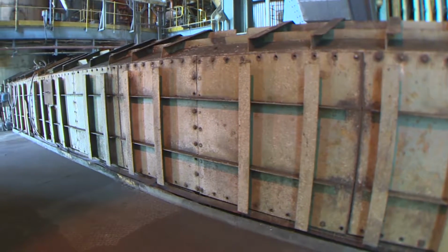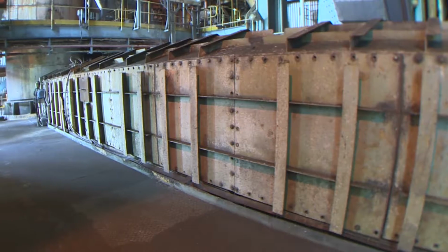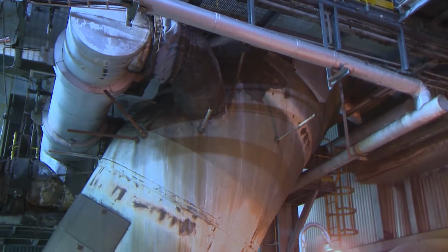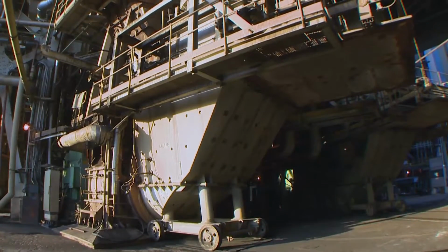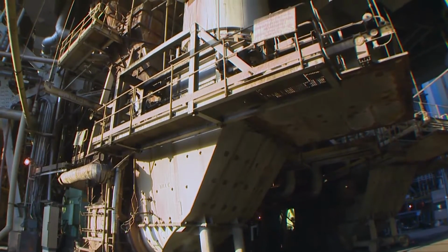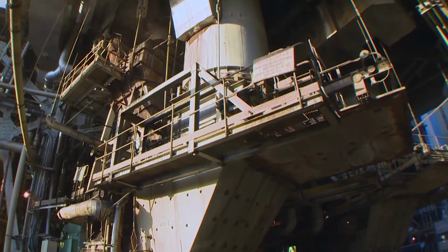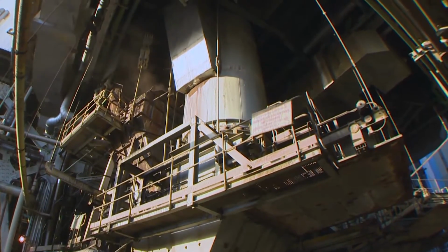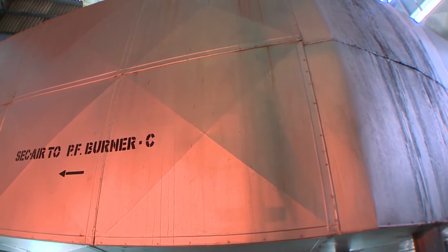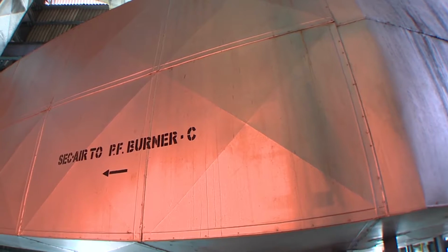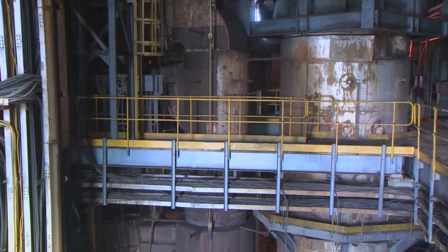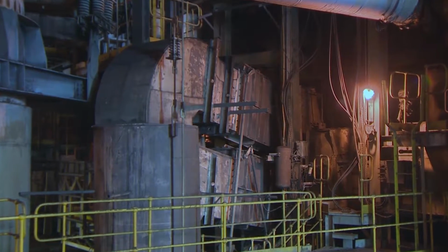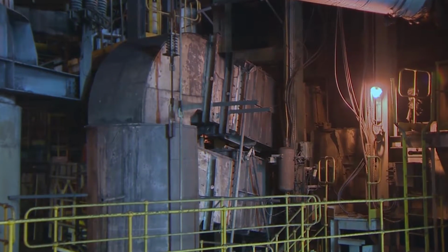The conveyor belt carries the lignite to resuction duct, in which flue gas is sucked from the furnace in order to dry the lignite. Then the lignite is pulverized in the beater wheel mill and carried to the lignite burner by the centrifugal action of beater wheel. The combustion air taken from windbox is thoroughly mixed with the pulverized fuel and admitted into the furnace through lignite burners, and complete combustion takes place in the furnace.